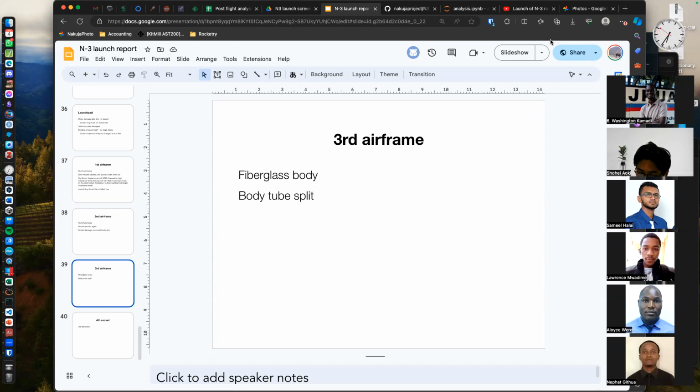Two, the fact that the motor could eject out of the airframe at that point also suggests that the reaction force was highly restrained, because if the chambers were at high pressure, the likelihood would be an explosion, more so on the rear side of the nozzle. If the back pressure is the driving factor and the pressures are not balanced, it means that the convergent divergent nozzle is not effective.